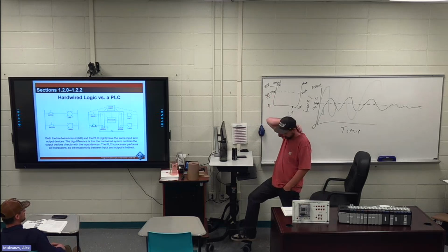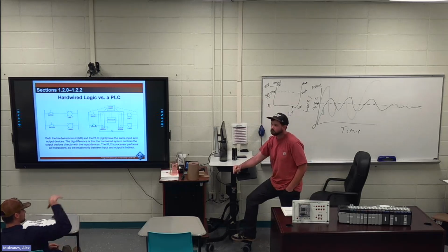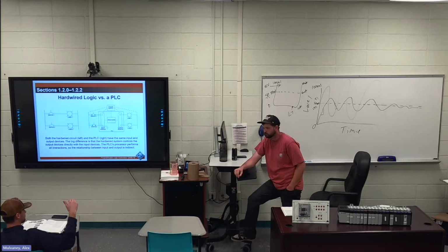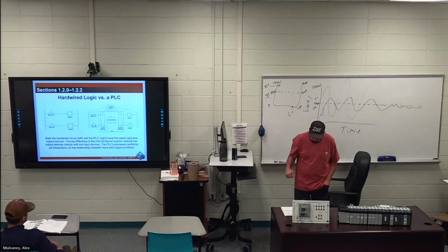So do you think it might be because that solenoid and the indicator are separate? They're wired in separate, they're brought back in separate. You think maybe there's something where if that indicator doesn't show that it opens after a period of time, it shuts off the solenoid? Yes. Yeah, that's probably what it is. Yeah. That makes sense. Yep. That would be my guess without looking at it.